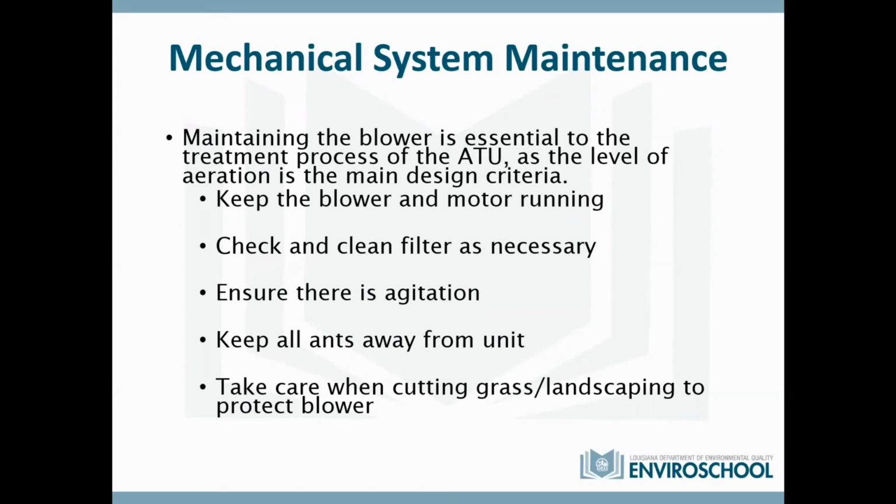And again, when you're cutting grass, don't have your grass cuttings going toward that blower. I've seen people actually use some pretty landscaping around these units, specifically around the blower itself. Not right up on it, because you want some airflow getting into that thing. You don't want to obstruct it. You don't want any kind of vegetative cover covering that thing. Keep it separate, but you can make like a barrier around it to keep grass cuttings from getting into it.